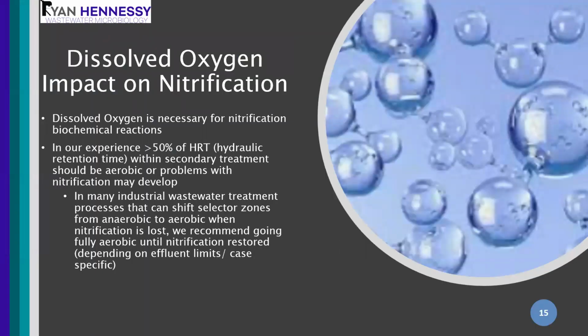So, as an example, there's a plant in Canada that I'm working with whose goal is not to nitrify. When it gets really cold, right now they're running about a 5-day SRT, and they're not nitrifying, and it's working in terms of preventing the overgrowth of Zoogloea bacteria, which is a concern there.